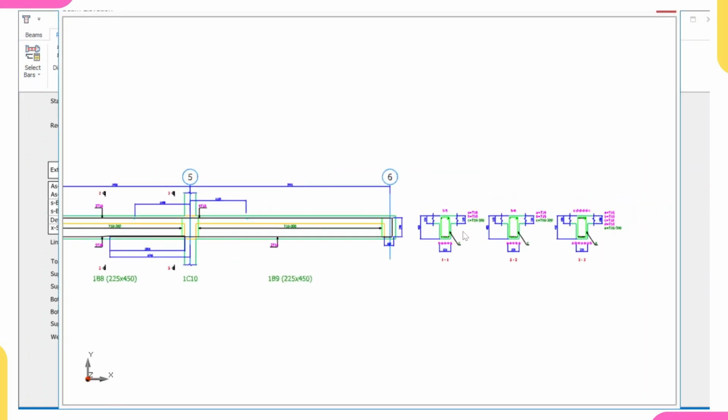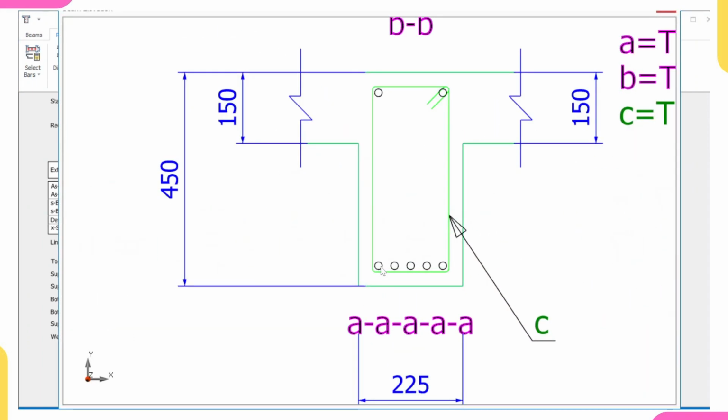So let me now explain it so you understand it. Look at what it means. The spacing between this bar and this bar is 18 millimeters. So you ensure that it is not less than 20 millimeters, because our coarse aggregate is 20 millimeters. That's 3/4. That's our gravel, 20 millimeters.